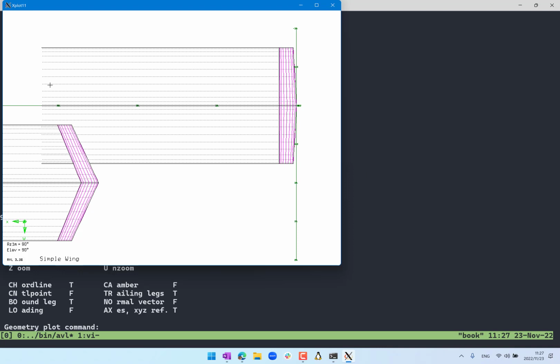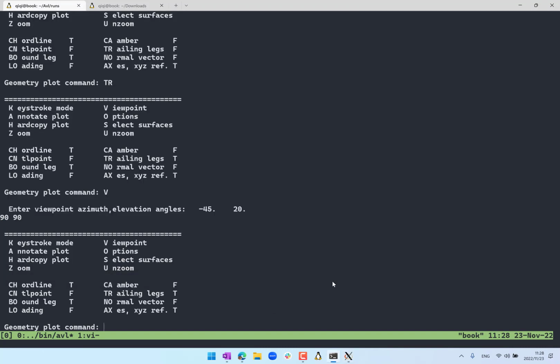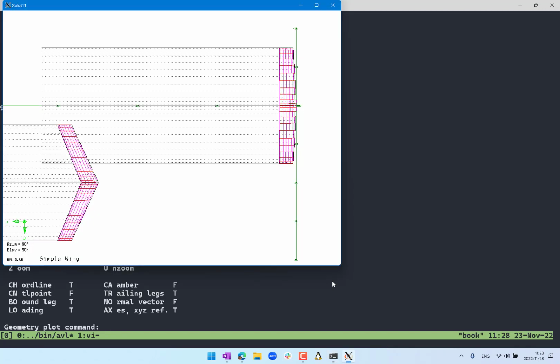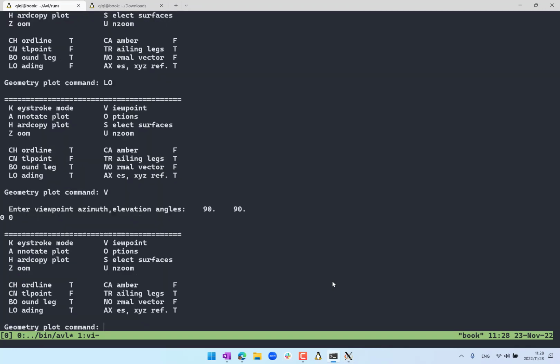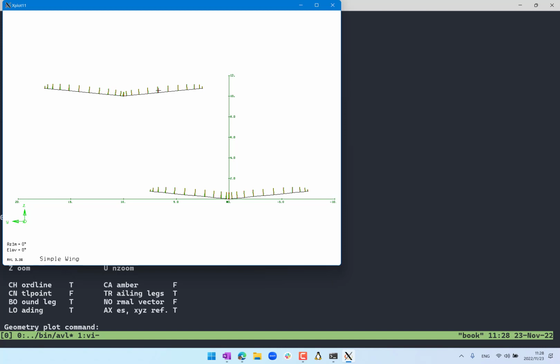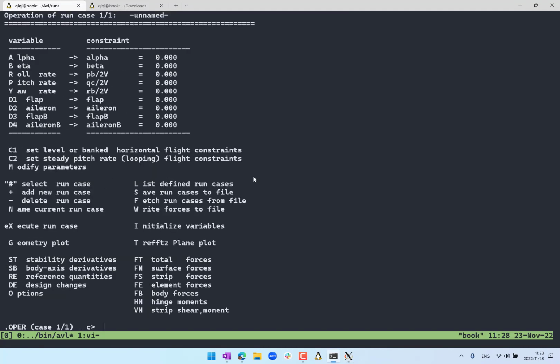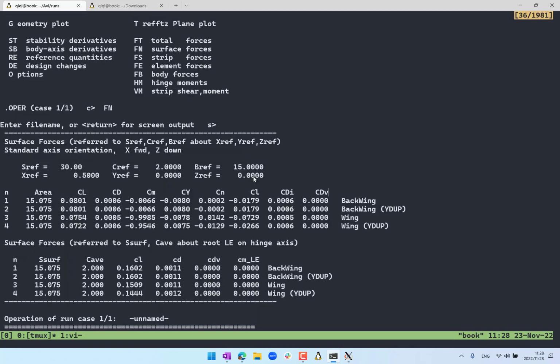Yeah, so okay, we actually do see the trailing vortices overlap with the hind wing, but this is still not good enough, right? Theoretically, you should have this vortex go a lot more downstream of this wing in order to have the full effect of these trailing vortices on the back wing, right? Okay, but if we turn on the loading and make the view angle 0, 0, we should already see these loadings are not going to be exactly symmetric. Especially if you print the total forces on the screen, you should be able to see that